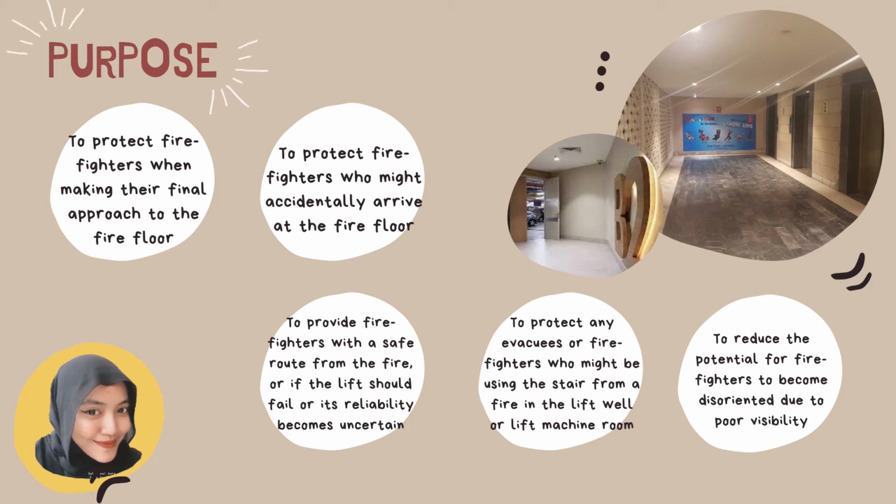So the purpose of the firefighting access lobby is, first, to protect firefighters when making their final approach to the fire floor, which means this gives some space for the firefighters to get their fire equipment ready before reaching the fire floor. Second, to protect the firefighters who might accidentally arrive at the fire floor.